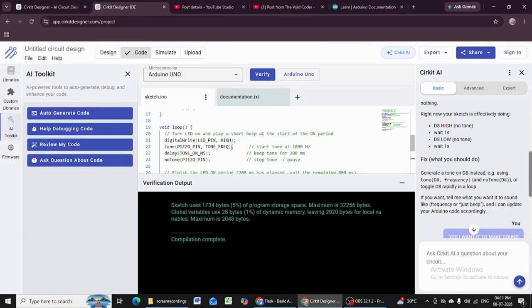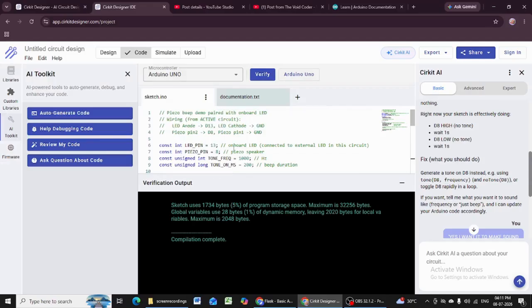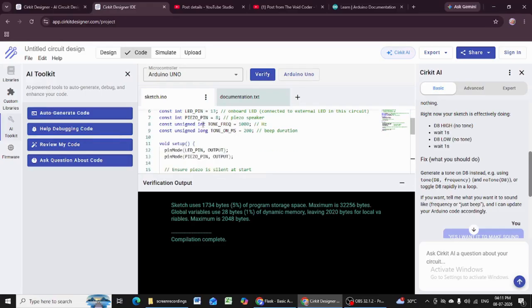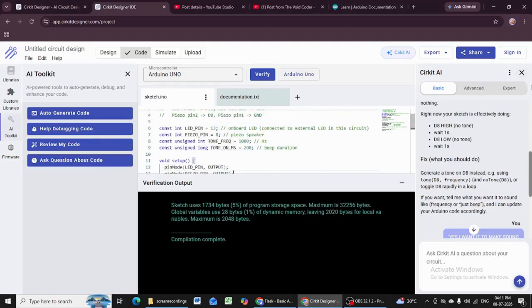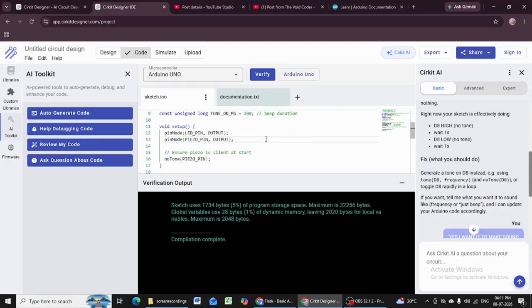So actually, I thought the buzzer would also work like the bulb, but no. I have to set the frequency here with a variable, and then I have to set the time span of that. As per my code, I made this mistake, like noTone. I had not given any parameter or threshold for that tone frequency. That's 1000, which the AI has given here.